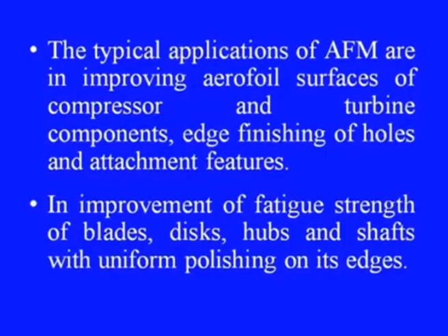The typical applications of AFM are in improving aerofoil surfaces of compressor and turbine components, edge finishing of holes and attachment features, and improvement of fatigue strength of blades, discs, hubs and shafts with uniform polishing on their edges. Also the adjustment of airflow resistance in blades, vanes, combustion liners, nozzles and diffusers, finishing of fuel spray nozzles, fuel control bodies and bearing components, and reworking the components to remove coke and carbon deposits and to improve surface integrity.